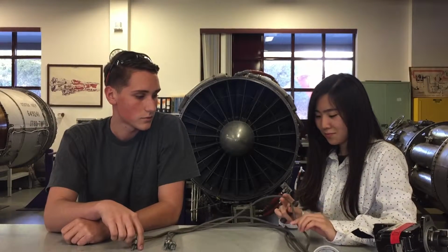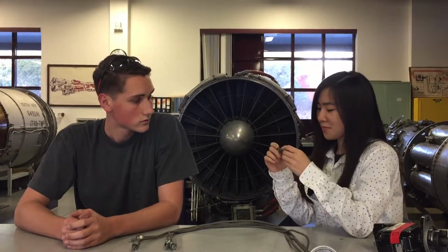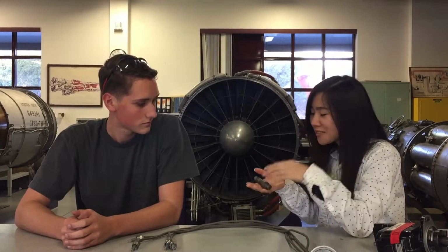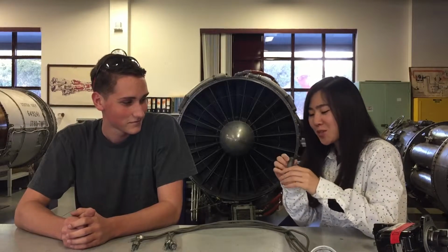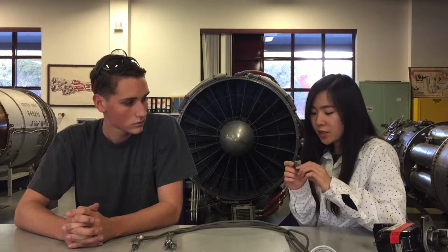What do you know about the spark plugs, Anna? So this is a spark plug. Not too heavy. This one is pretty much made of a metal shell outside, and inside you can see the insulator to prevent current leakage, and the electrode assembly. It's really simple. Once this one gets high voltage, it creates a spark and burns the fuel and air mixture in the cylinder.